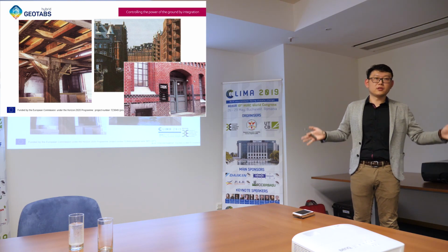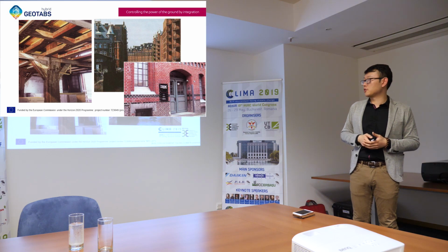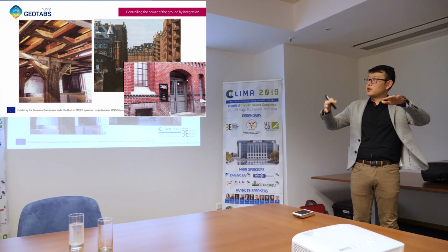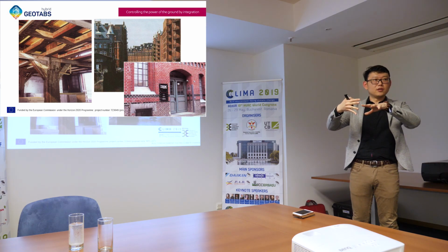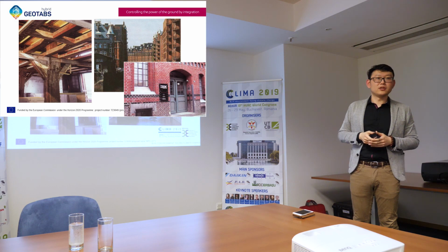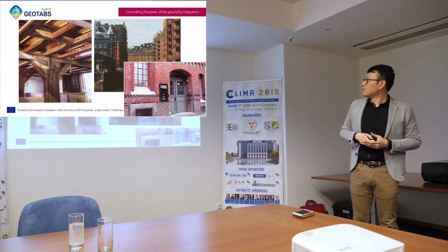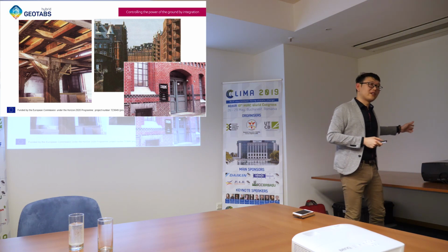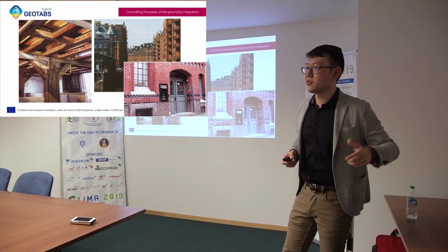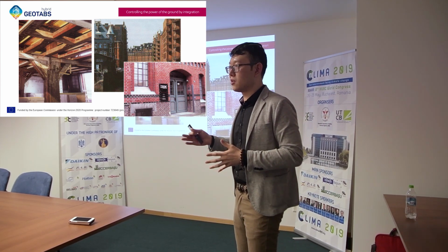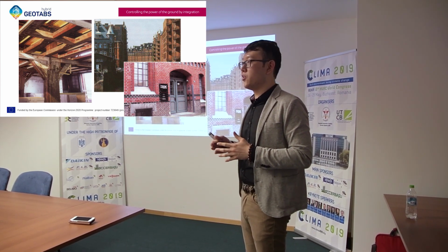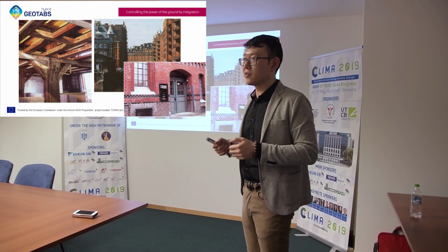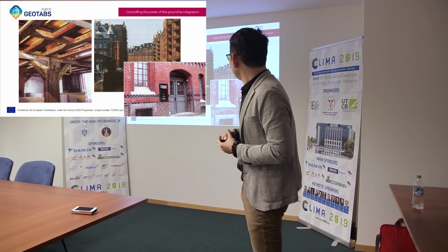So basically, you cannot put extra insulation on the external wall and the internal wall. And the ceilings look like this, so it has a lot of beams. This is an old classical way of constructing in terms of building physics. And we are not allowed to drill, which means that it's hard to drill into the wall, and they have nice bricks, so you cannot do too much on the internal wall, which means that radiators are not the best solution because you still need to have some kind of interruption to the envelope.